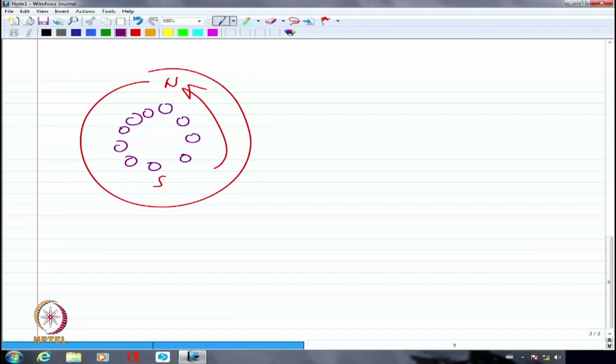So I'm going to have a rotor current because of the induction. That rotor current is going to cause again three-phase currents flowing through the conductors in the space distributed winding of the rotor, which will cause another revolving field to be set up. That revolving field will try to interact with the stator created magnetic field, and that is going to produce a torque in the process of aligning with each other. That torque essentially will oppose whatever is the root cause for the torque production.